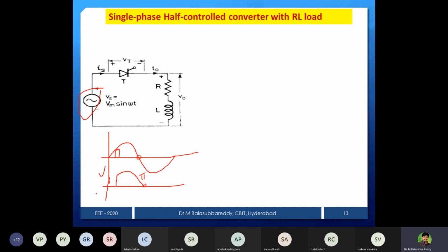This is the voltage. Now I will represent the current. Just carefully observe this. We are starting at this point. Before that current also 0. Now current will be gradually rising because it is storing the energy. Current will be rising. And after that, once it reaches pi, the polarities will reverse. Earlier upper side is plus, lower side is minus. Now upper side is minus, lower side is plus, because energy dissipation is going to take place. That's why the current will gradually decrease.